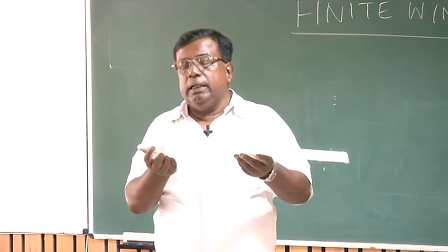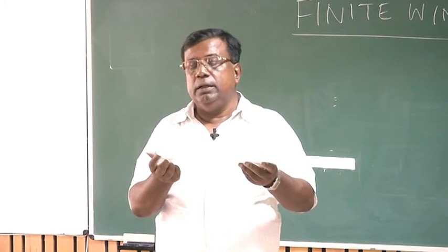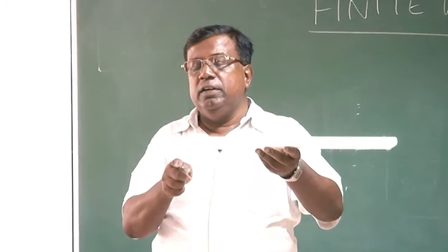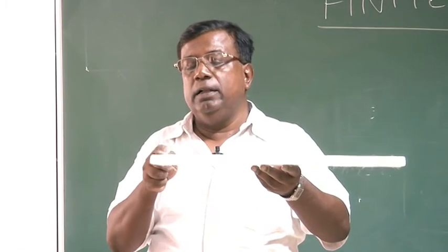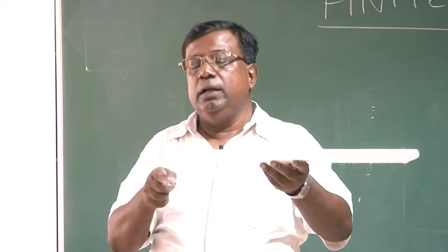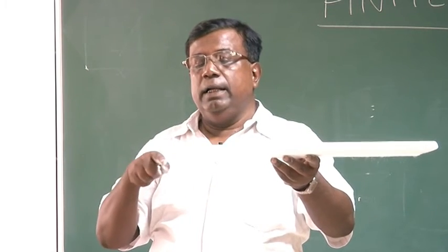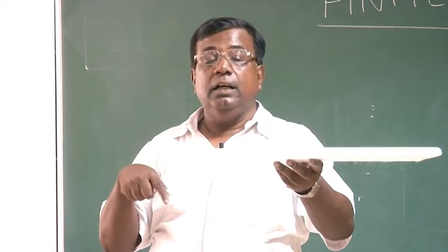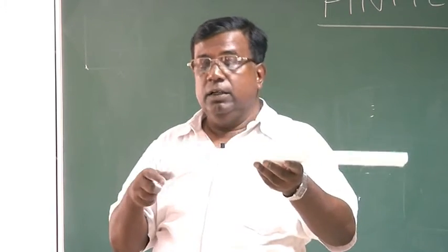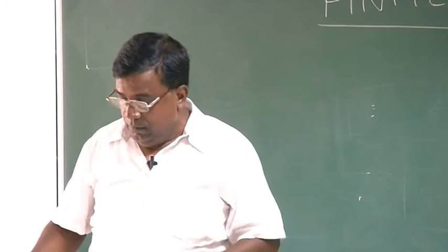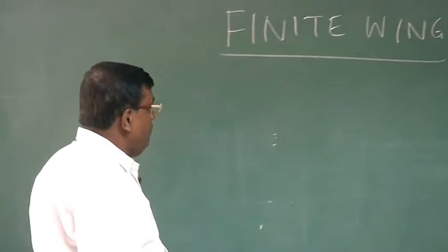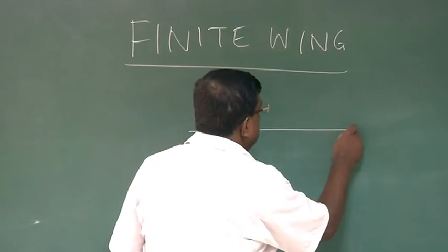So at the tip of the wing here, because there is a pressure difference between the bottom and the top, there will be vortices, and they will draw kinetic energy, rotational kinetic energy, at the cost of the engine energy. So there is a drag, and we call it vortex drag.